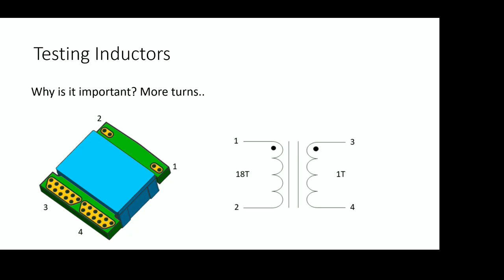And the other thing they do, we didn't mention earlier, one thing about coils is when they're inductively coupled between the primary and secondary, which means they don't physically touch each other. And what that allows for also is a lot of isolation. And we didn't talk too much about that. That's another reason why they use a lot of coils and transformers, is that they can take out parasitic components across the inductive coupled transformers. So here they might be stepping down or attenuating something, but you're also isolating, which means, if you're running an AC circuit, it'll couple AC but block DC, so you'll get that noise component out.